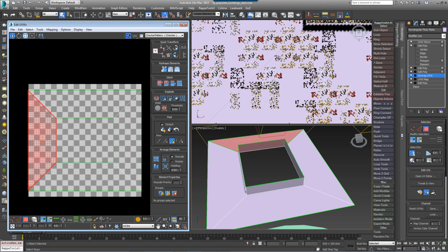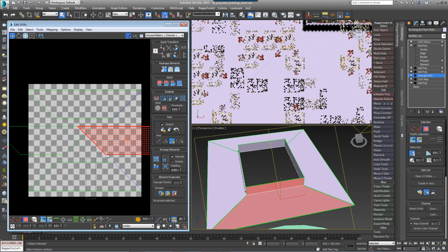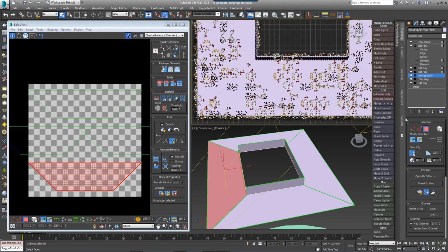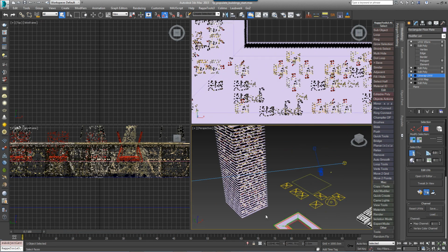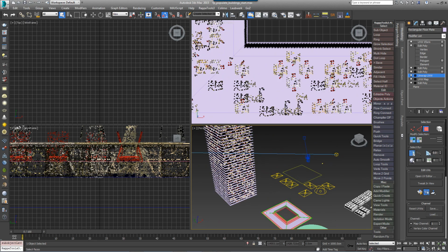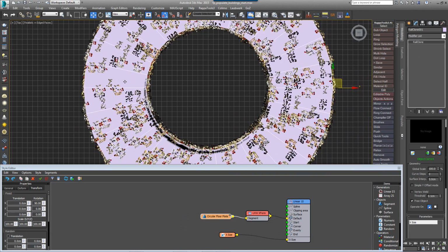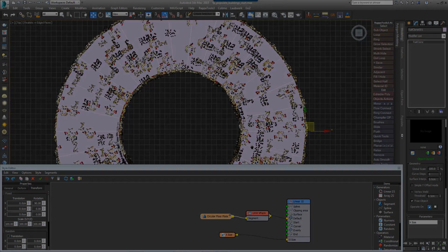Open the UV editor, and what we need to do is to make sure the outside face of the building aligns with the U axis for each side. To do this, detach each side and rotate it so that they're all the same. Now if you look at the desks, you'll notice they remain aligned with the exterior face of the building. If you swap the rectilinear floor for the circular one, you can see this effect more clearly.